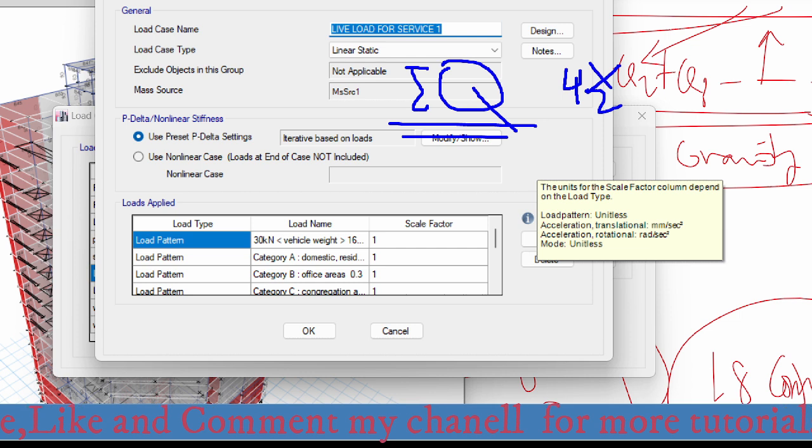Phi 2 should not be used here because this live load will be used for the combination of gravity loads. That is why I am excluding phi 2. So all the factors are 1. It is not 0.3. 0.3 is not used here. That is 100% of the variable loads are taken into account.